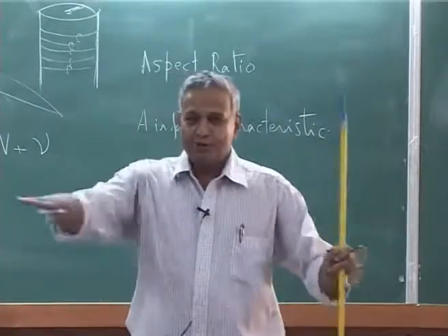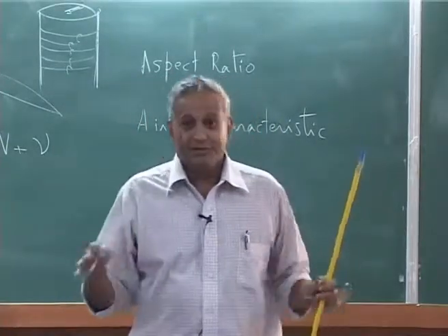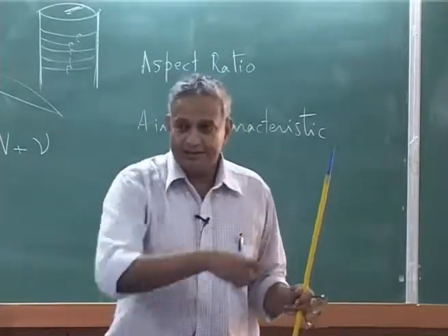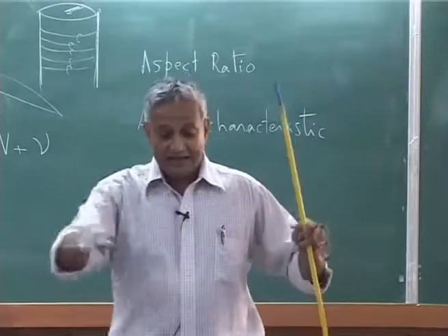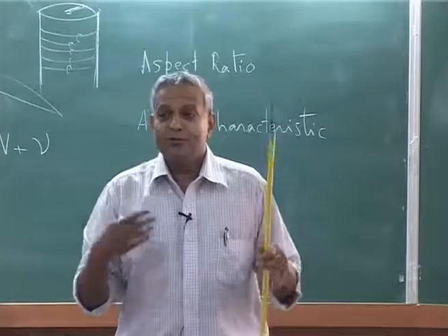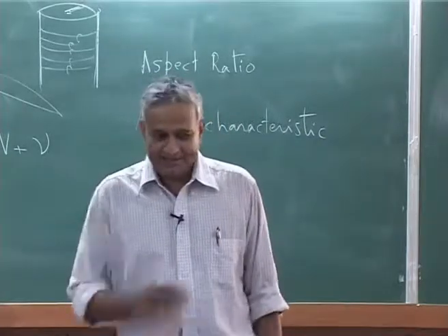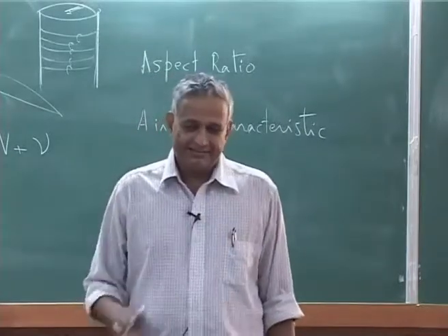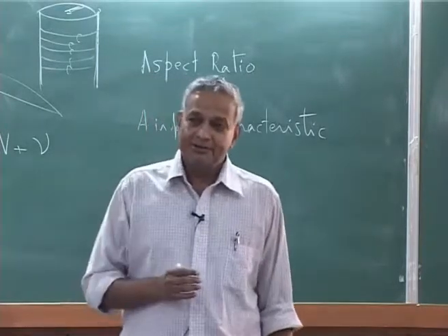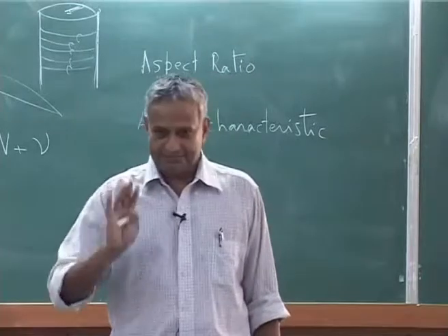not the uniform inflow. That is what we did in the momentum theory. The flow over the disc is constant at every location, that is uniform inflow. Later you will see, that is too gross an approximation, let me have non-uniform inflow.